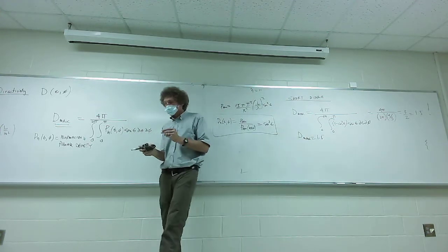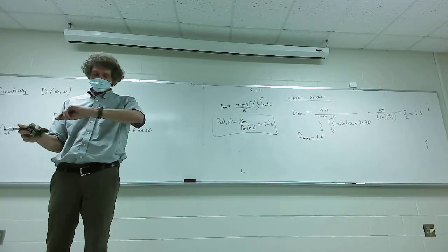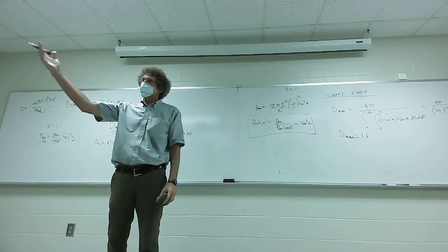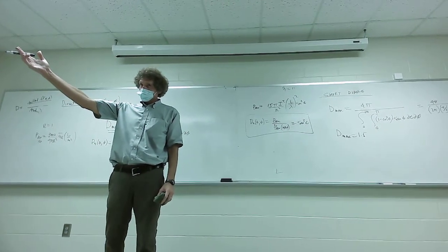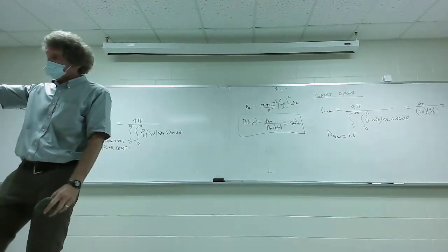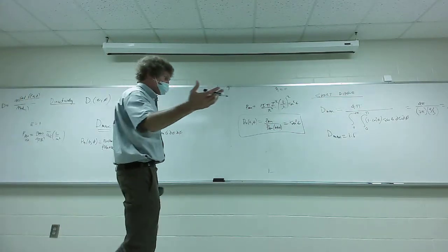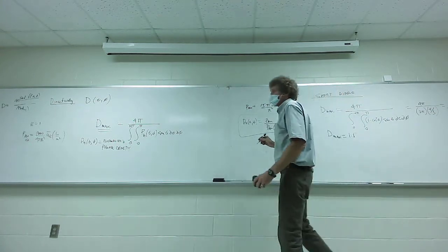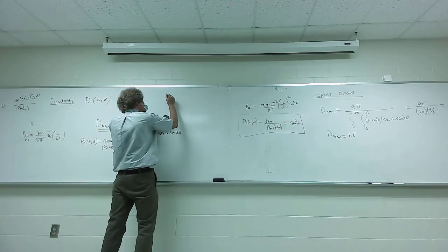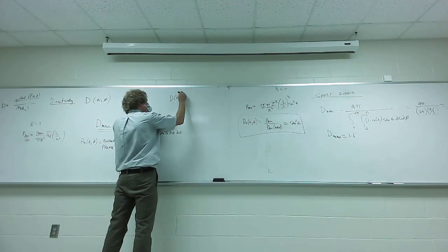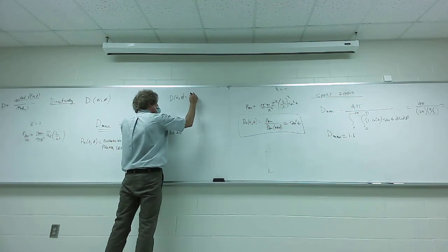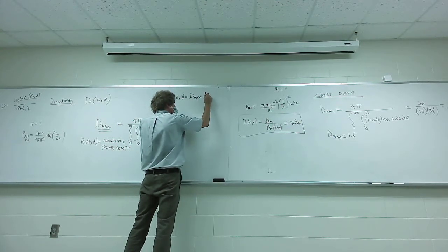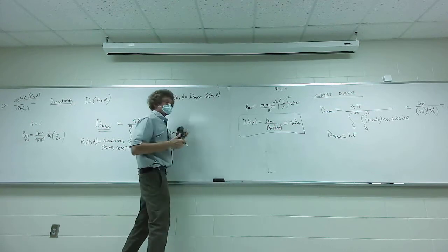That's not quite the whole story with directivity. I want to make sure you see this example. That's the maximum, right? So how do you get the directivity at any angle? You know, if you had that directivity and you had the total power radiated, you could get the power density, and I'm going to do that next. Here's how you do it. This is a little out of order, but you can say D as a function of theta and phi, and this is true in general, is D max for that antenna times the normalized power density of the antenna.